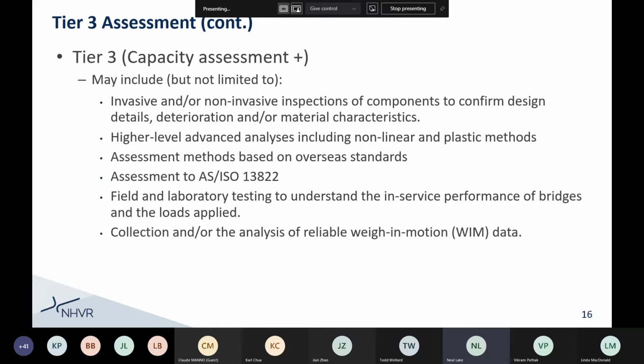We could do some testing to understand the material capabilities and characteristics. Often the compressive strength is much stronger than what we initially thought, or what was designed. So on a drawing, when we specify a strength of concrete, this is a lower bound that we use when we design, but the actual strength of concrete might be much higher.